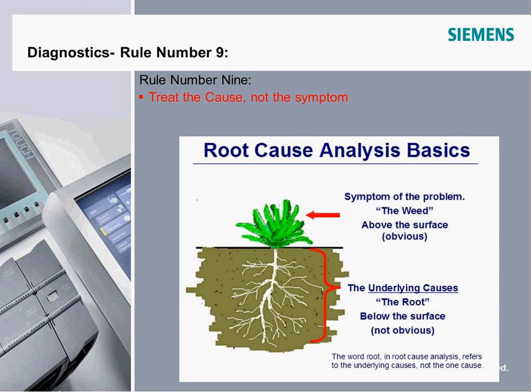We have all heard stories about bad car service places where, if you look at the itemized list afterwards, they replaced half a dozen things, and chances are that it was the last one that was the problem, and all these other things got replaced even though they weren't needed. But also, as I mentioned, these can cause other problems too, especially with programmable and configurable devices. I mean, everything down to sensors nowadays have adjustments on them and so forth. Just going out and trying to fix things by replacing them, based on what looks like the symptom, is going to end up giving you a lot more problems than you originally had.